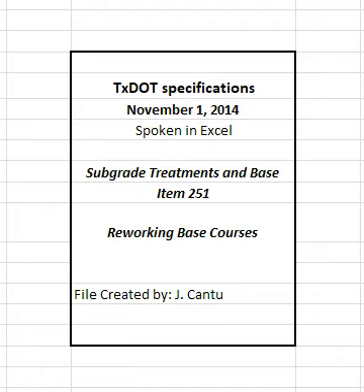Rework, recompact, and refinish material that fails to meet or that loses required moisture, density, stability, or finish before the next course is placed or the project is accepted. Continue work until specification requirements are met. Perform the work at no additional expense to the department.